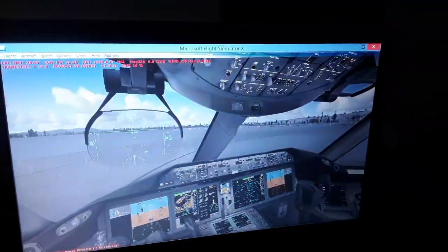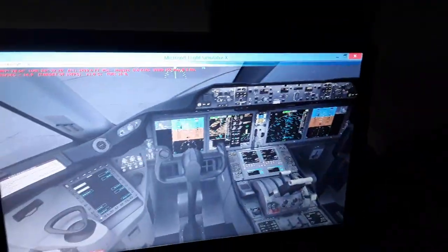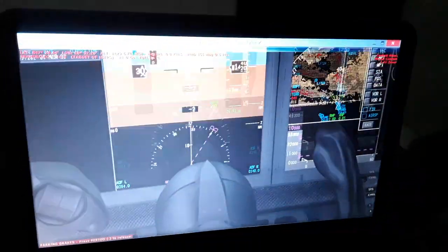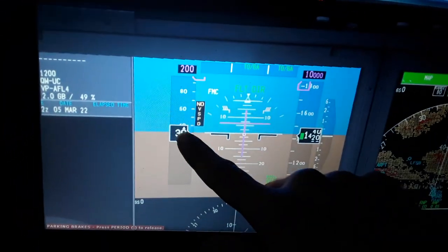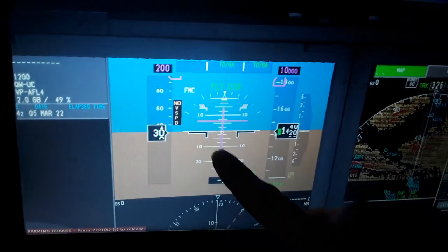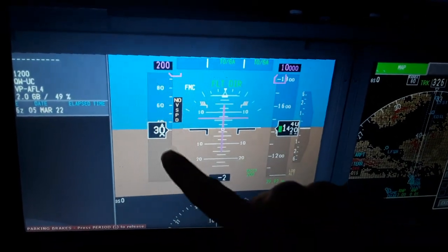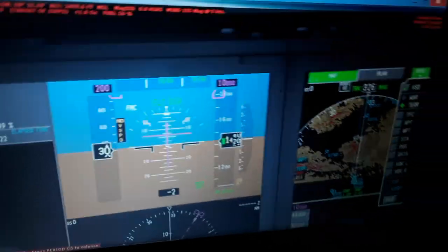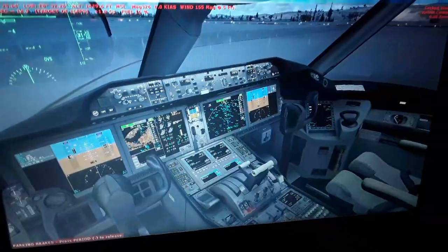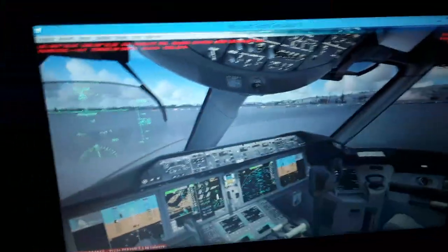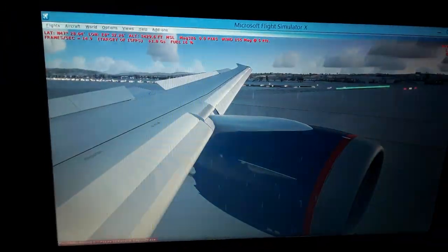The airflow will become detached in the top surface of the wings, so you can monitor here always. You have here the airspeed indicated in the primary flight display, and you can see also here the airspeed selected from the autopilot directives. You see the stall speed is going to be here, with a yellow and red indication. You will need to have an airspeed above the stall speed always when flying the aircraft in a high angle of attack. So it's going to be less than that.